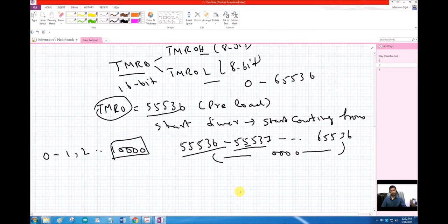The microprocessor will do it automatically when there is no such label in my program. So that flag is being checked automatically at the back end of the processor. Some dedicated hardware is checking that flag at the back end, and that is the case when we use the interrupts in our peripheral. So we will discuss the interrupts of timers in our next lecture.